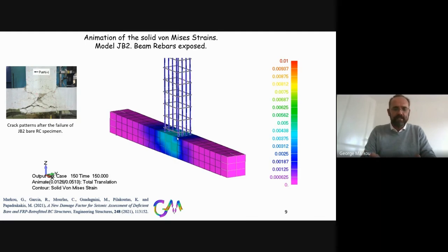Because you have an embedded rebar, you calculate the stiffness matrix, and that stiffness matrix is added to the stiffness matrix of the hexahedral element in a direct way after you transform it. So if you affect the stiffness matrix by affecting the Young modulus of elasticity of the embedded rebar, then the hexahedral element is also affected, and the contribution of the embedded rebar is also modified, and then you have the effect on the overall mechanical response of the structure.